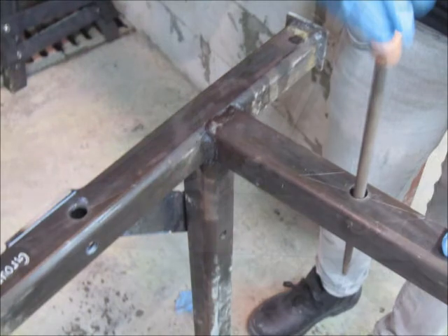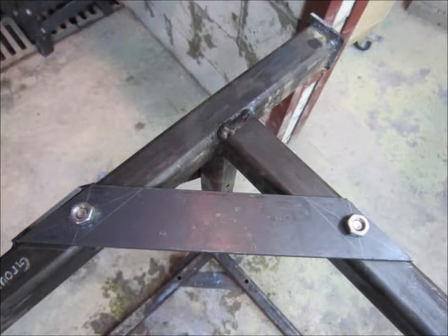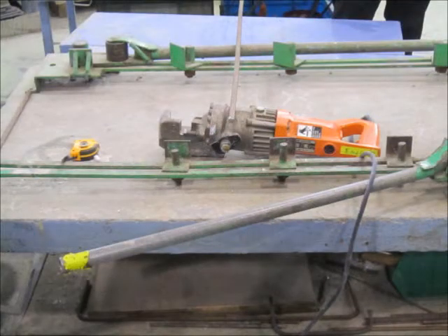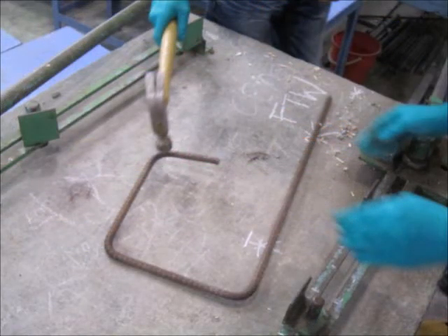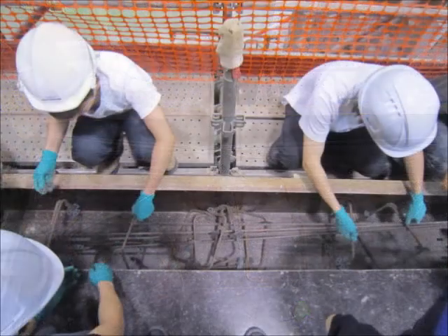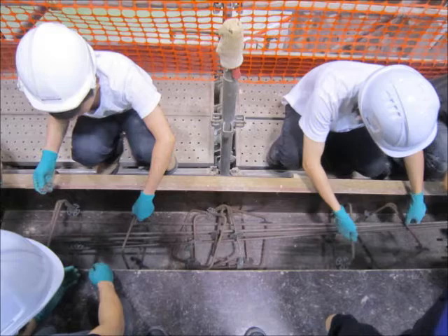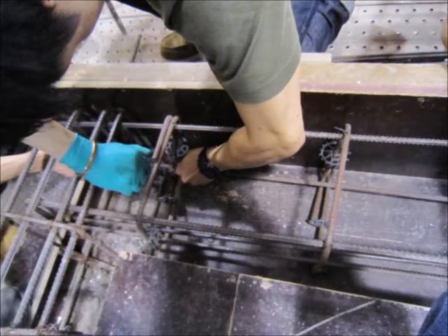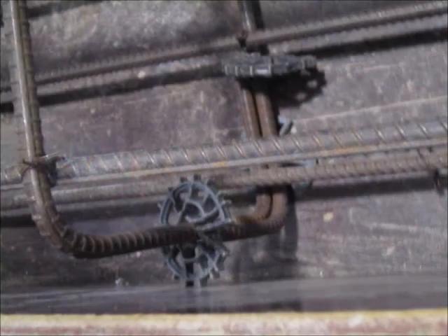The function of reinforcement in an RC structure is to achieve better performance of the structure in resisting loading in compression, tension, shear, and torsion. When connecting steel bars, we can overlap the bars using couplers or welding, but the most common method is to overlap the bars. In this session, we are required to tie the beam reinforcement.